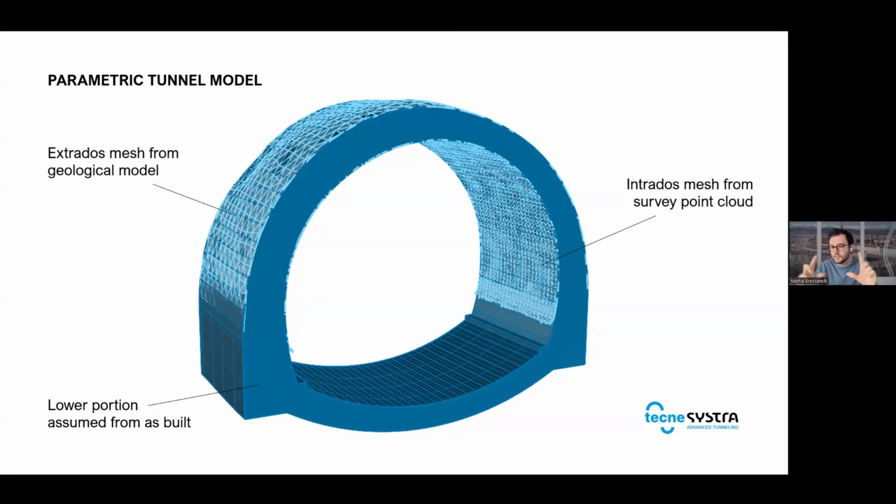Of course, it scales horizontally slightly because the arch, the crown, changes shape slightly because it adheres to the intrados mesh. But also you can move up and down the reverse so that it matches with data you could have from surveys from boreholes done in the roads.